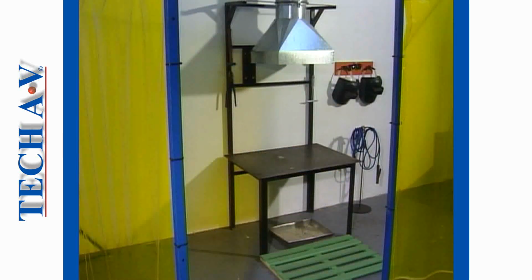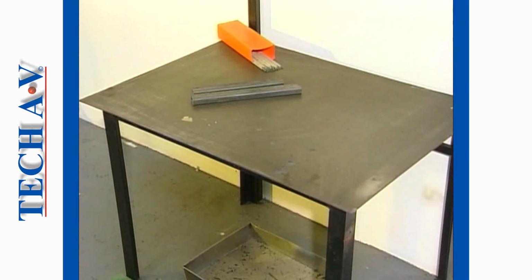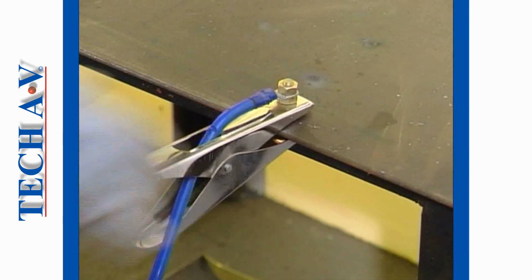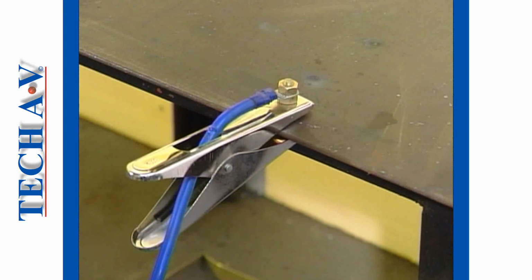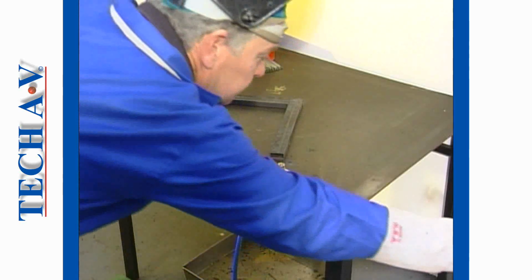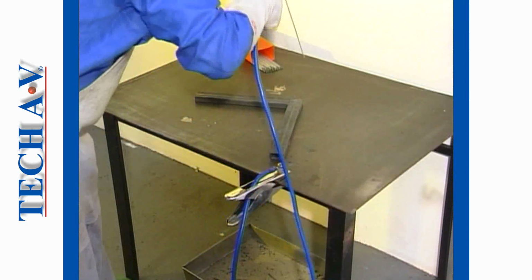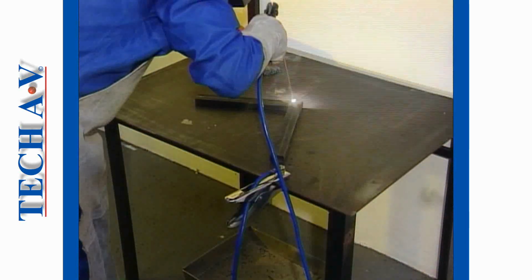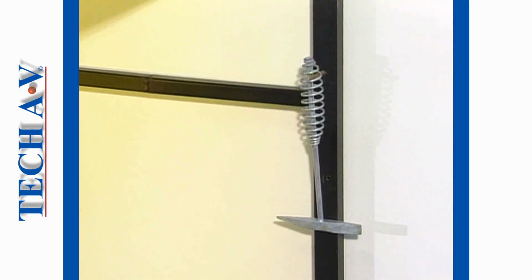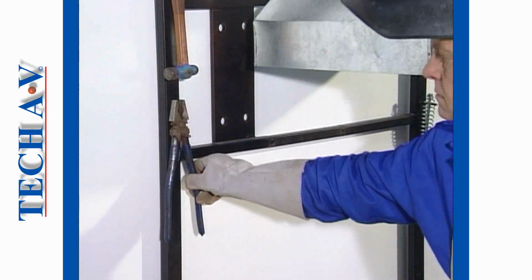The basic skills and procedures for performing SMAW processes can best be learnt in a welding bay. The welding bay consists of a steel-topped workbench. The work lead of any suitable welding machine can be attached using an earth clamp to the steel top, or may be permanently attached to part of the structure. Steel workpieces may be set down onto the metal surface, and as long as the metal is clean, welding can be performed on the work. Provision should be made in the bay for your tools and other accessories to be stored conveniently when they're required.